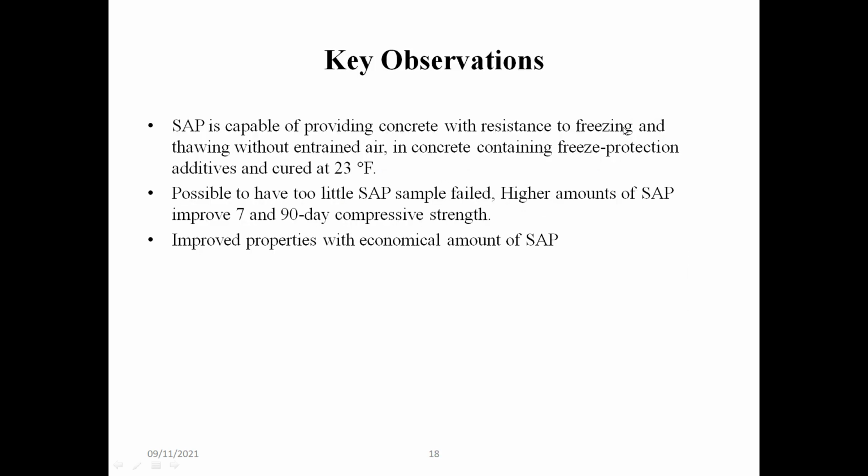So now we are going to note down some key observations. SAP is capable of providing concrete with resistance to freezing and thawing without entrained air, in concrete containing freeze protection additive and cured at 23 degrees Fahrenheit. It is possible to have too little SAP if the sample failed. A higher amount of SAP improves 7-day and 90-day compressive strength. Improved properties with an economical amount of SAP.